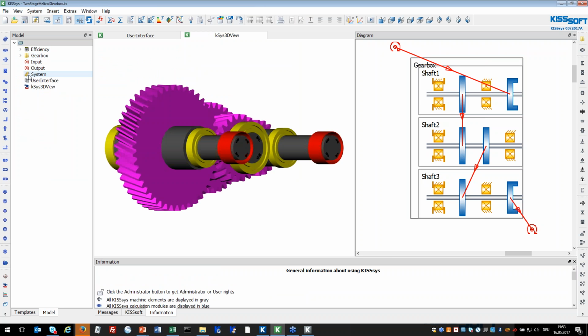It's to combine the different material failure probabilities which you can have in a system coming from the different standards. Like for the shafts, mostly 1% is used, for the gears 1% material failure probability, and for the bearings default 10%, which can also be changed in our software. And we use this to compare all these elements in a system.